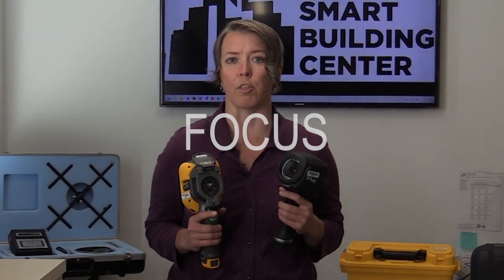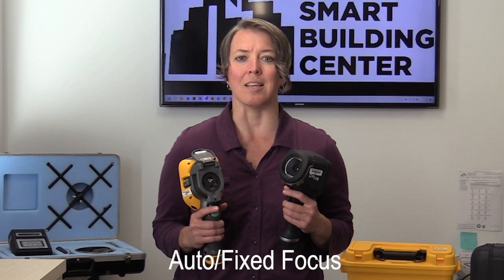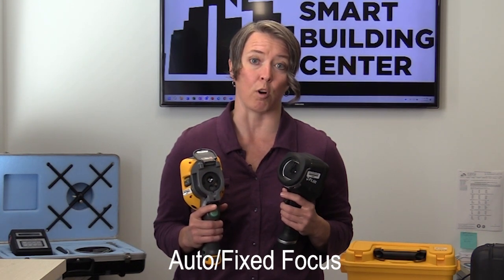So let's talk about focus. It's important for a thermal image to be in focus for accurate diagnosis. Cameras are typically made with either an auto or fixed focus or a manual focus option. With a fixed focus, you want to make sure that you're aware of the minimum focus distance for your specific camera.